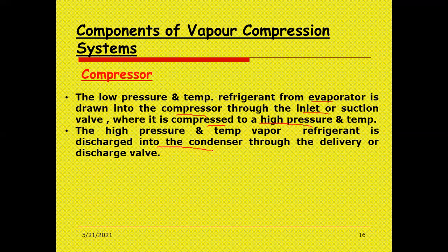Next point, then the high pressure, high temperature refrigerant is discharged into the condenser. So what happens here? The refrigerant is passing from the compressor into the condenser through the delivery or discharge valve. So that is the main activity done by the compressor.